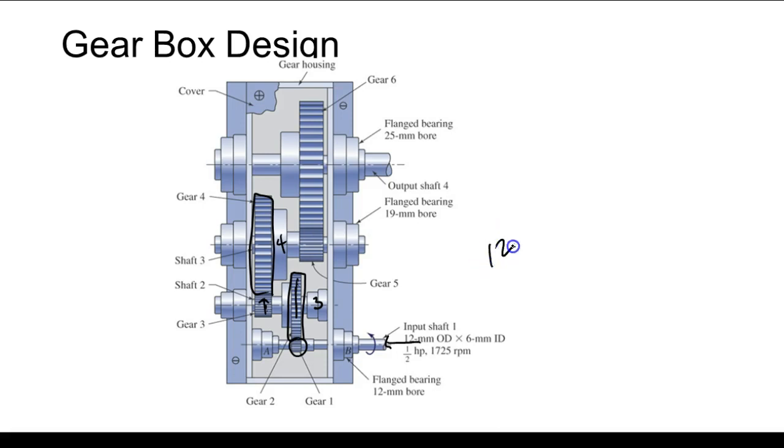Yeah, 12. You multiply them together, right? And then this is turning at the same speed, so we're not changing the speed, but the speed of this gear would be 1/12 of the input. So speed went down, torque goes up. And then we take this one, and this is an even bigger gear. So let's say this is 5, then what would be my total torque multiplier? Yeah, my total torque would be 60, and my speed would be 1/60th of the input.